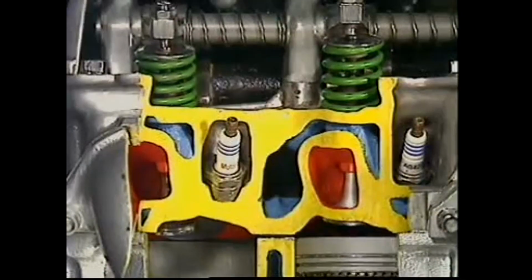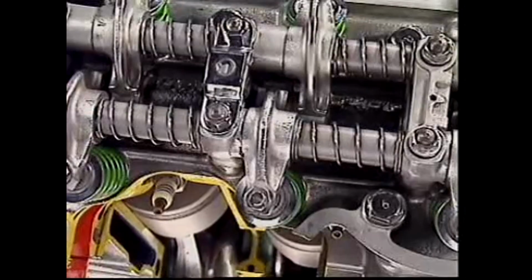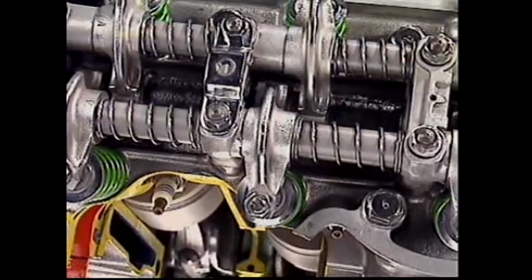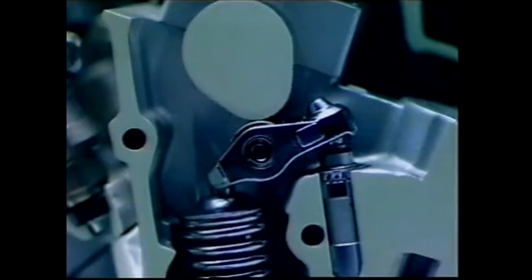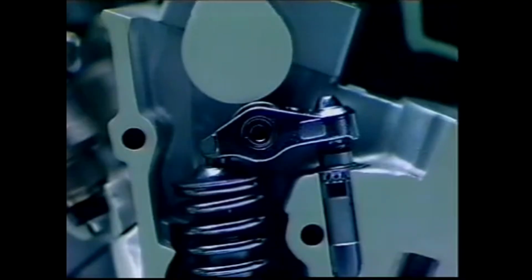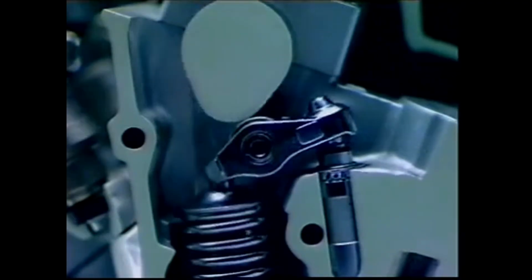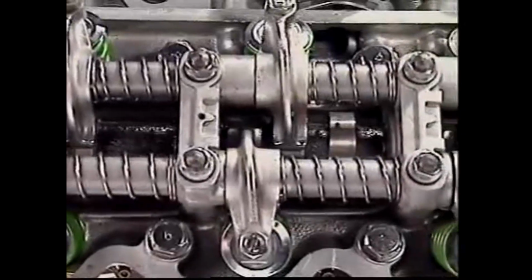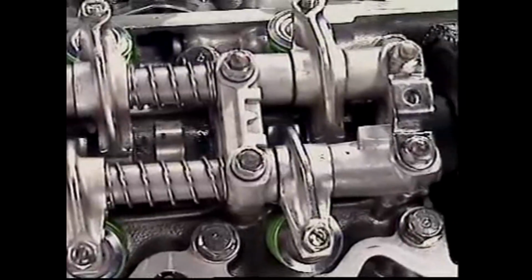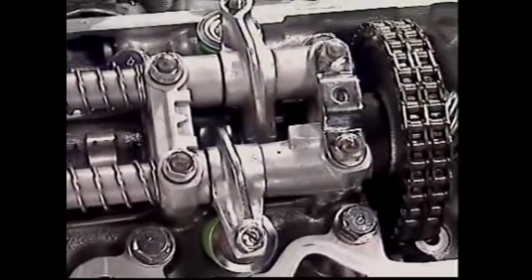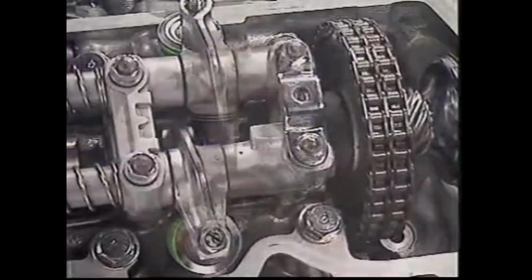The valve is held in place by a valve guide with a spring on its stem. A rocker arm is attached to a stationary shaft that allows the arm to pivot. The rocker arm compresses and releases the valve spring so that the valve opens and closes. The valves need a system to control how they work. This is done by using cams. A cam is a lobe on a shaft. It's specially shaped to open the valve, hold it open, and let it close.